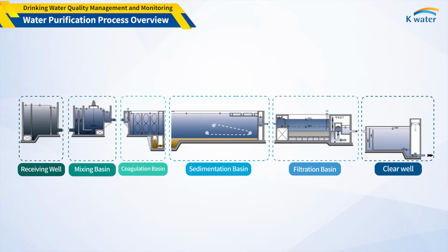So, what does the water treatment process consist of? Various unit processes can be used for water treatment. But in Korea, conventional processes based on filtration and disinfection are mainly used. Sometimes these can be called a standard process. This is a process that produces a large amount of water in a short time through a complex process. It is combined with chemical precipitation, filtration, and disinfection process.